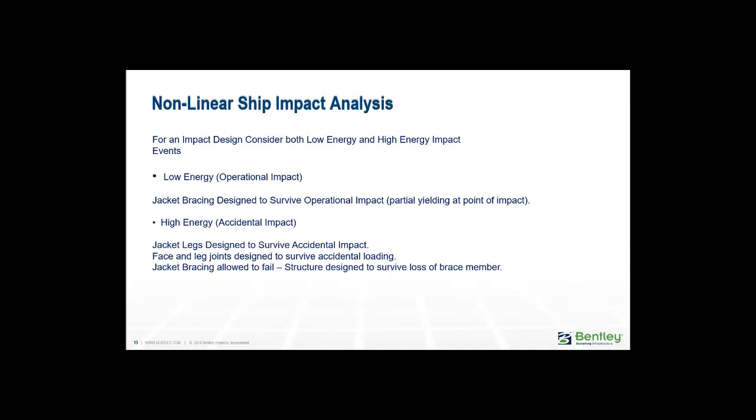For nonlinear ship impact analysis, we designed for both low energy and high energy impacts. The low energy is also referred to as an operational impact, where the jacket bracing is designed to survive operational impact. Partial load yielding at the impact point is allowed.